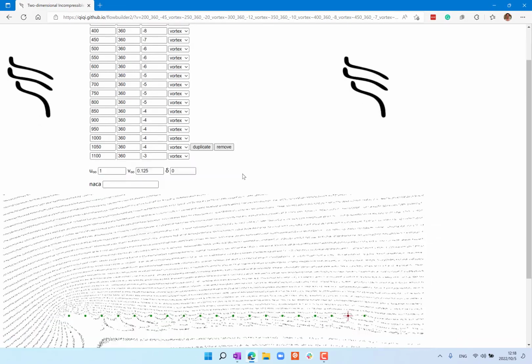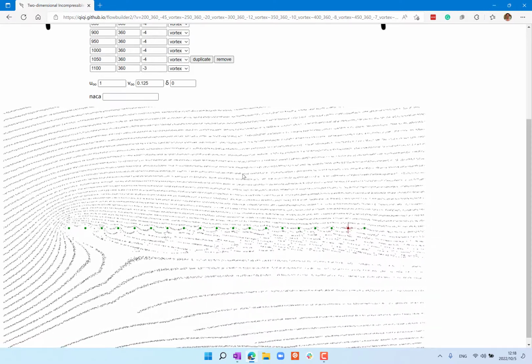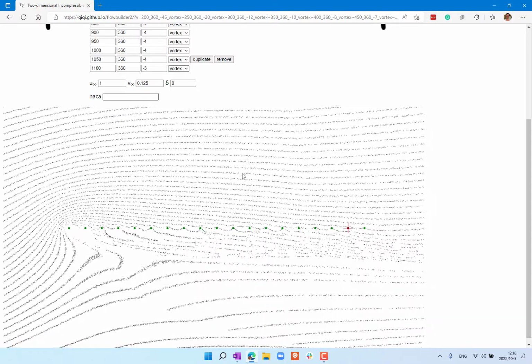No, right? Because the flow would be going down across the airfoil because I decreased it. The flow is the sum of multiple elementary flow fields. I didn't change these flow fields; I only changed the free stream component. So now the free stream doesn't have enough y component to stay parallel. The flow is going down